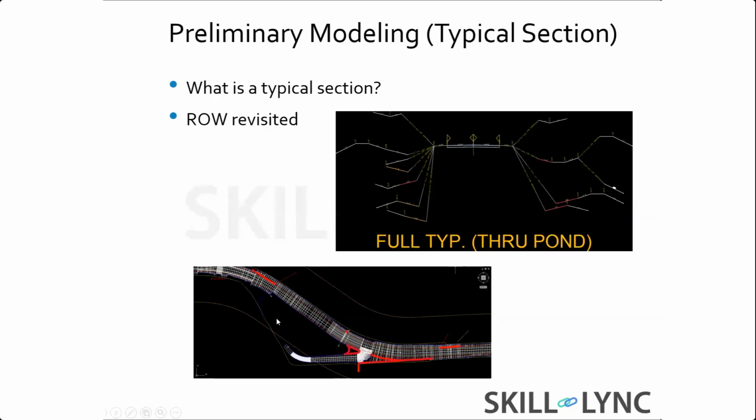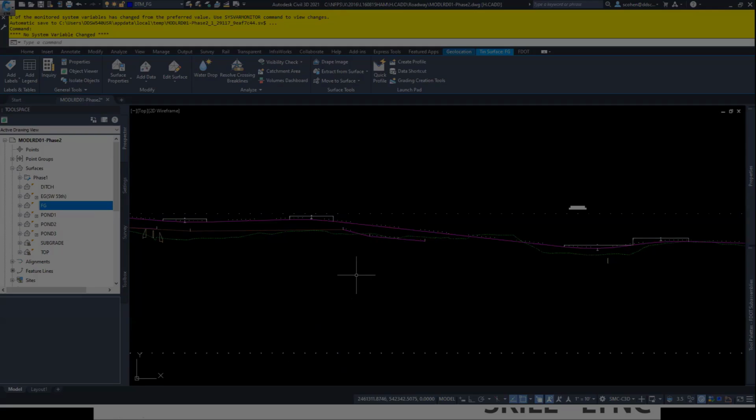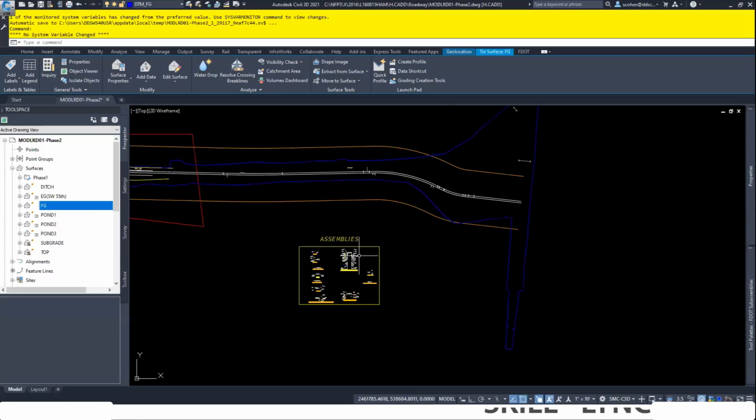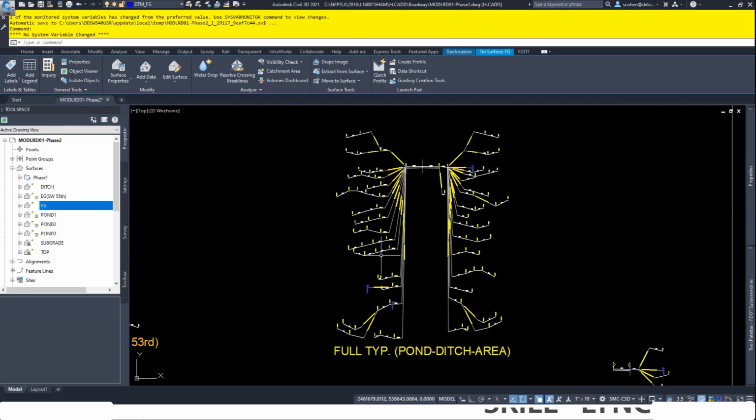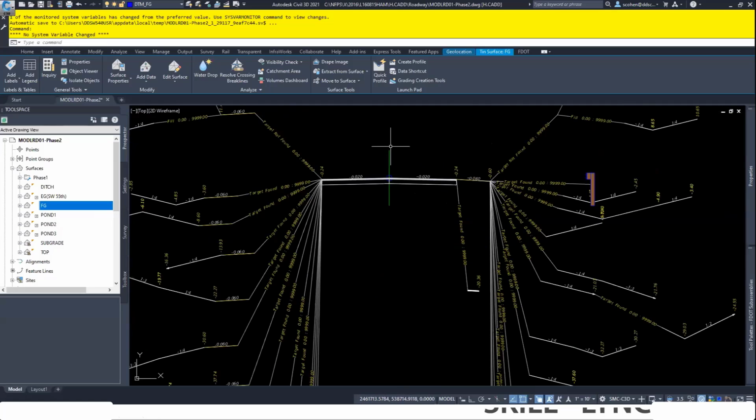All right. And just to kind of show you that here, this project here is basically what's called a Civil 3D. That's the civil engineering software by Autodesk. This is an assembly. So your assembly is your actual road. And then all these components here are what's called sub-assemblies.